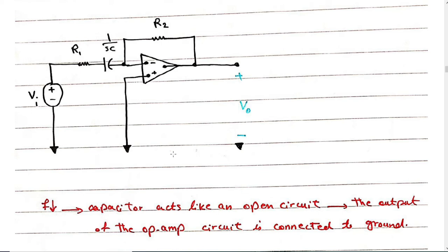Okay, so when it is open circuit, what will happen to the output voltage? Why? Why 0? Because VP is 0, so it means Vn is 0. There's no current coming in from the source. Yes, there is no current, so Vn is 0. So it means Vout is 0.